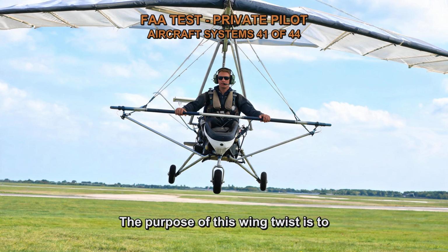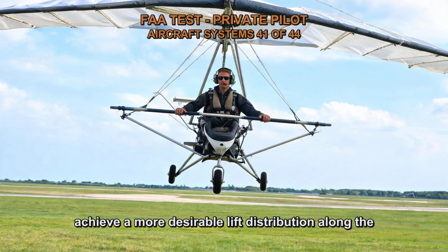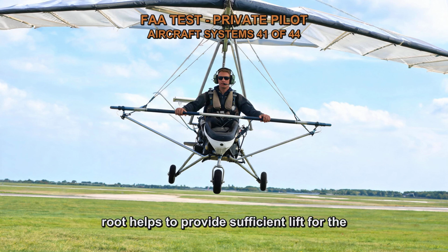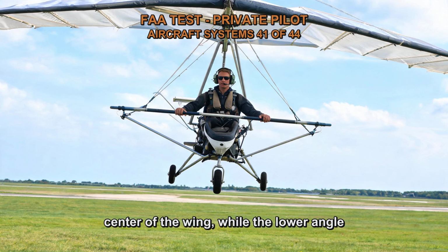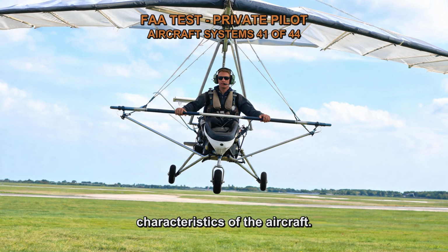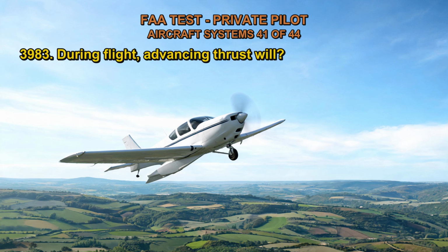The purpose of this wing twist is to achieve a more desirable lift distribution along the wingspan. The higher angle of attack at the wing root helps to provide sufficient lift for the center of the wing, while the lower angle of attack at the wing tips reduces the likelihood of tip stall and improves the roll characteristics of the aircraft.